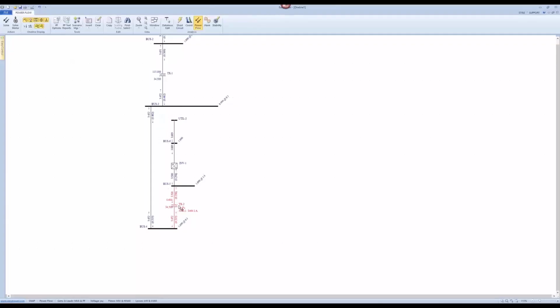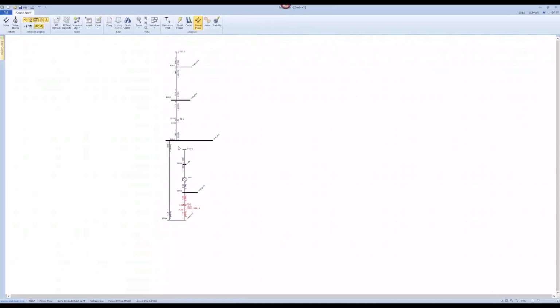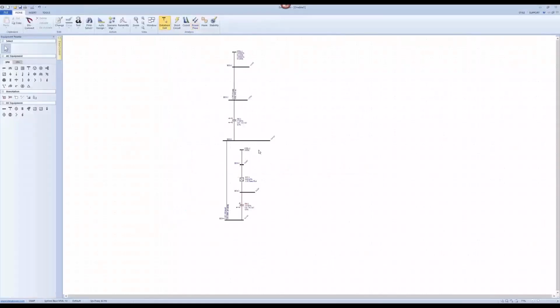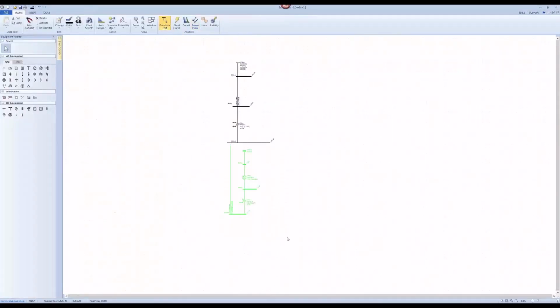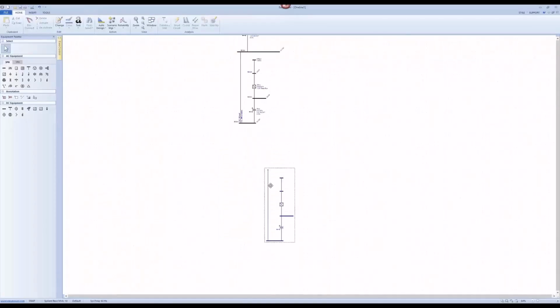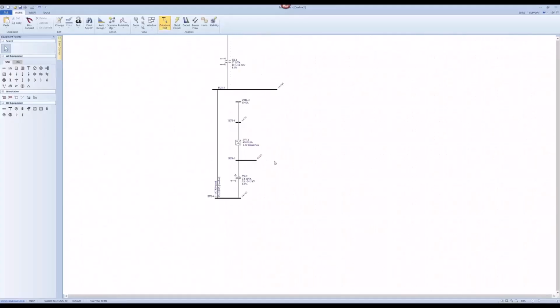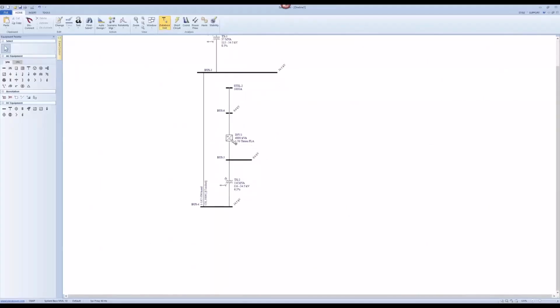If I scroll down a little bit to make some room for the quality display. Okay, now I have my collector cable section of one inverter done. So the next thing we need to do is very easy in EasyPower, right? Copy, paste. This is a typical fun thing to do in EasyPower when you construct a one-line. But it looks like we are done with the power flow, but we are not done with the harmonics yet. So we need to enter the harmonics data and then start the copy paste. Otherwise, you will be missing the harmonic spectra in the inverter, right?